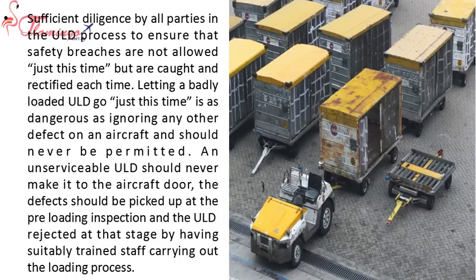Sufficient diligence by all parties in the ULD process to ensure that safety breaches are not allowed just this time but are caught and rectified each time. Letting a badly loaded ULD go just this time is as dangerous as ignoring any other defect on an aircraft and should never be permitted. An unserviceable ULD should never make it to the aircraft door. The defects should be picked up at the preloading inspection and the ULD rejected at that stage by having suitably trained staff carrying out the loading process.